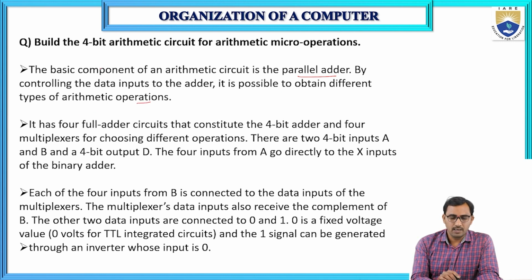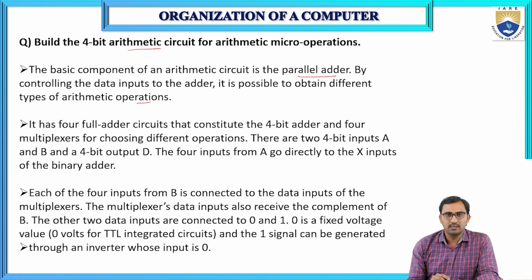So here we are going to build a 4-bit arithmetic circuit. Using this arithmetic circuit, it will generate various arithmetic micro operations, that are addition, subtraction, add with carry, subtract with borrow, increment, decrement. So all these various arithmetic operations are generated by using this 4-bit arithmetic circuit.